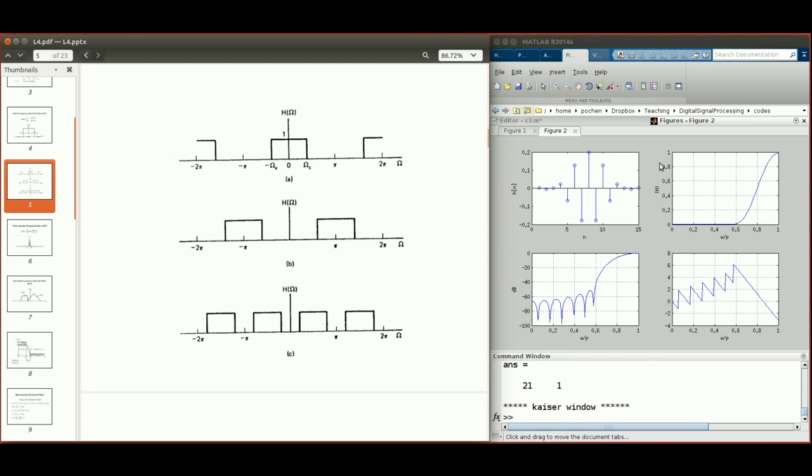Because the FREQZ function only constructs the positive frequency, the negative frequency is not plotted. But you can imagine on the negative frequency side, because it's symmetric, you're still going to have a boxcar. So you're also expecting something going down there, that's the other half of the filter. And that's plotting it in the linear scale.